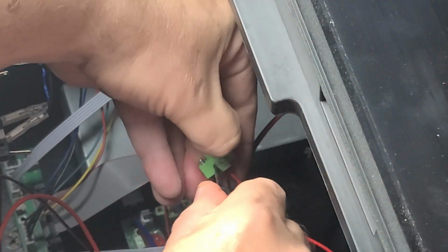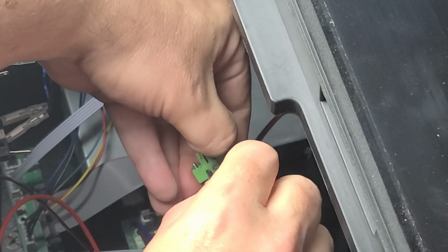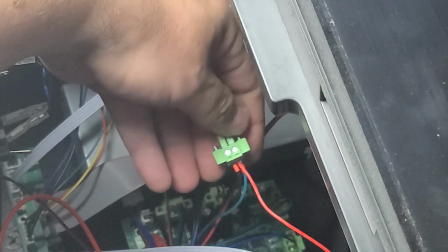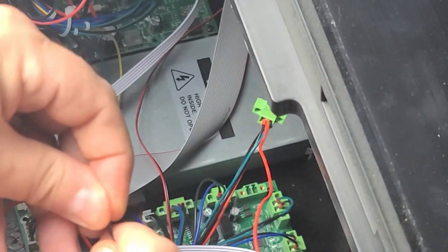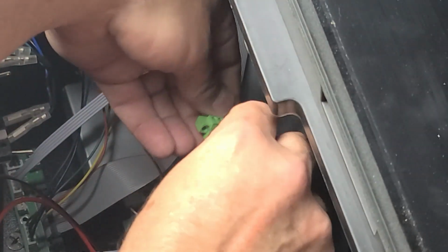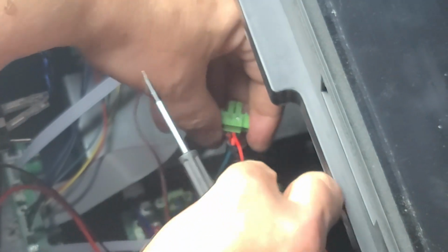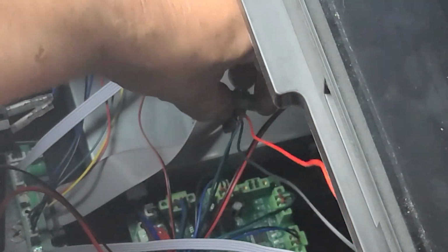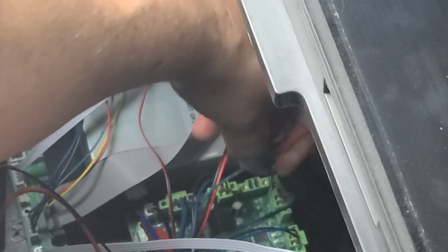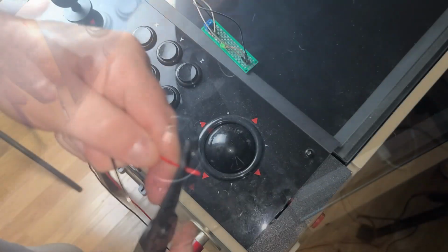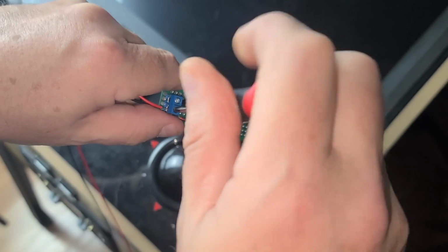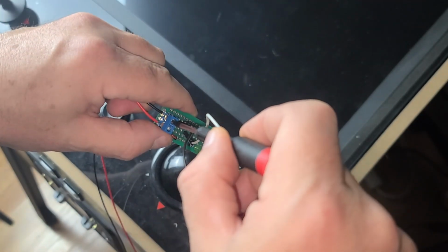And I've routed 2 wires into the cabinet for positive, or red, and negative, black, into and out of the Legends 4KP cabinet. Here I'm just screwing those two wires into the terminals on the solenoid board. Then reattach the connector to the solenoid board. I'll reinstall the control panel, strip and connect the two wires to the screw terminals on the custom board, and